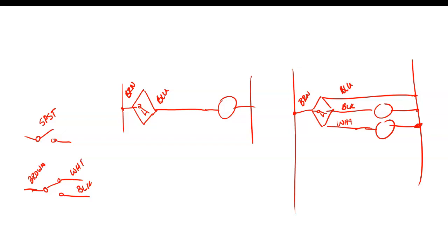Well, when I get down to 24 volts, which is the preferred voltage now used in industry, and why? Why is it 24 volts? It's a lot safer. And why DC? Because the internal portion of the controller is electronic, and it operates off DC. So when we had AC PLCs, they actually have a power supply inside of them, right?